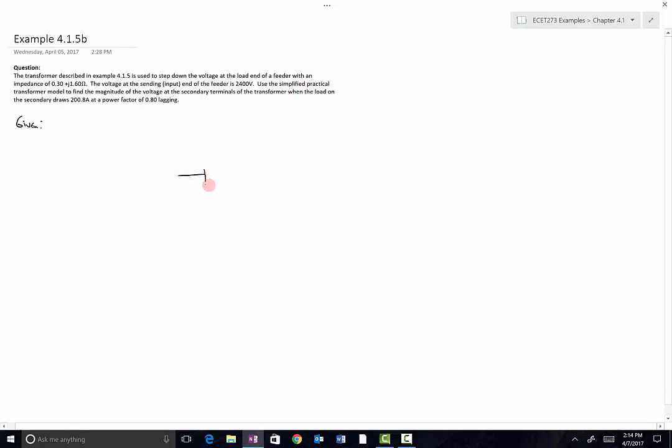We've got a series impedance, the primary resistance and primary leakage reactance, which was 0.72 plus j0.92. So that's ZP equal to R1 plus jXL1 there.